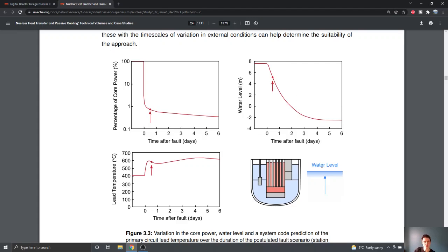So for this model, as you can see, it's quite a complex system, and actually if we wanted to simulate this entire event with water boiling away and slowly being reduced and switching to air cooling, we'd need a model to run for 5 or 6 days. And for many of you who carry out CFD analyses yourself, you know that it's not going to be possible, even with perhaps the best modern computers, to have a large CFD model and to run that for 6 days of simulated time. It's too long. The model will take years and years to run.